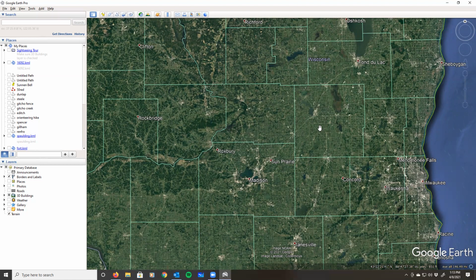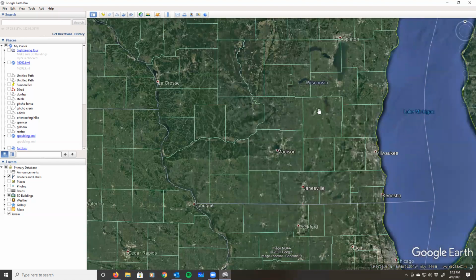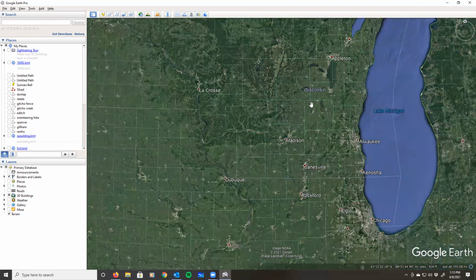So you don't have the distortion in the projection that you do when covering a larger area like the Illinois East and Illinois West. There's a lot more distortion there, with a scale factor of about 99.995 feet grid equaling 100 feet ground measurement.